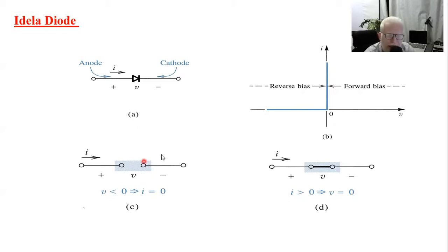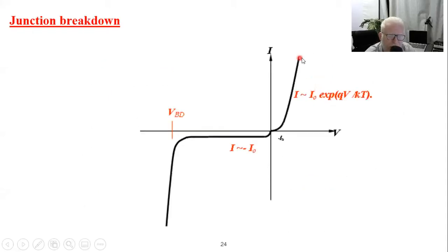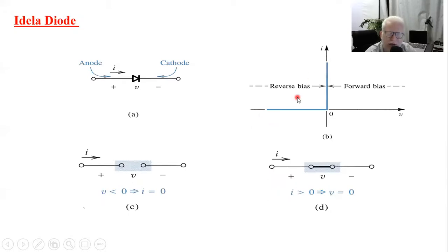However, as you can see here, this is a very simplified model, as we are neglecting all these IV characteristic features and approximating only in this on-off state. That's why we can consider the ideal diode the simplest model for an electrical diode. And in order to get more and more accurate results while dealing with your electrical diode, you have to consider a little bit more complex model.